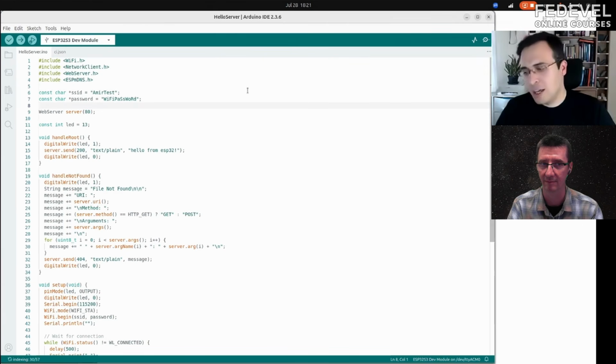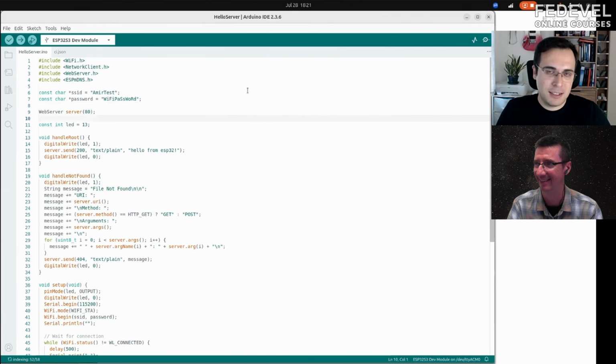It gets hard coded. For a final product that you ship with ESP32, you want it to be programmable by the user itself. Or there are different methods of provisioning. It's called Wi-Fi provisioning. That usually happens on these devices. Because this module supports BLE, the easiest way is to use the Bluetooth connectivity. So a mobile phone, for example, can configure the device so it connects to a Wi-Fi, instead of the user typing the SSID and password. But there are different methods, and basically it affects the usability of the device.